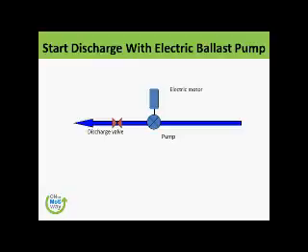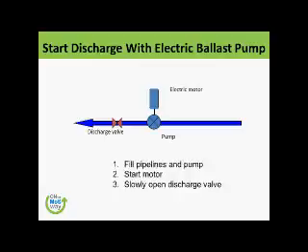So we need to keep the valve either fully closed or very lightly or crack open. So once the back pressure is developed inside the line or a pump, we can start discharging. So key thing: fill pipelines and pumps, start motor, and then slowly open the discharge valve.